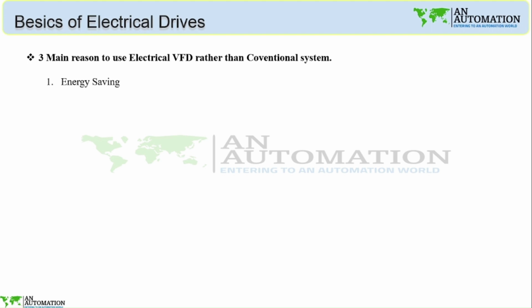In such applications, energy can be saved by operating the motors at low voltage while running at no load and light loads. When a motor operates at full voltage at no load, core loss has a large value. Reduction in the voltage increases the copper loss but reduces the core loss by a larger amount. This results in energy saving.